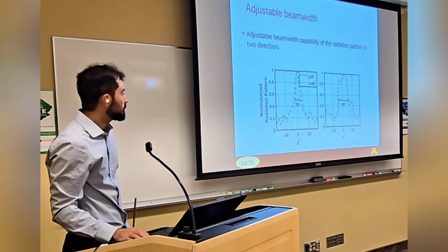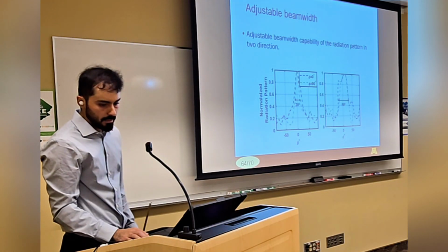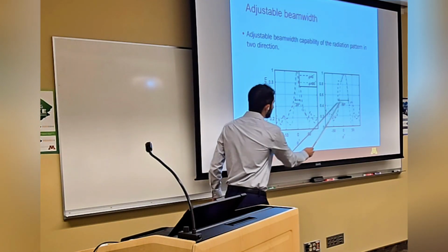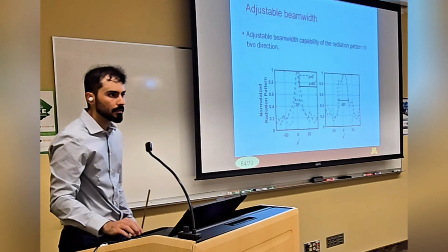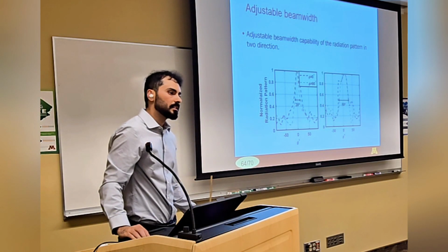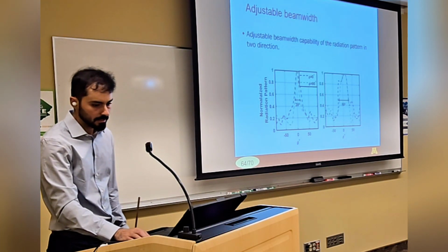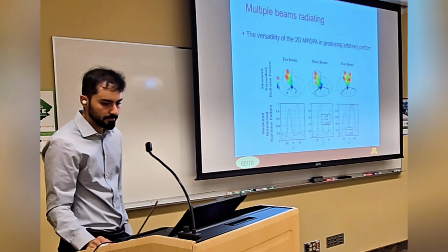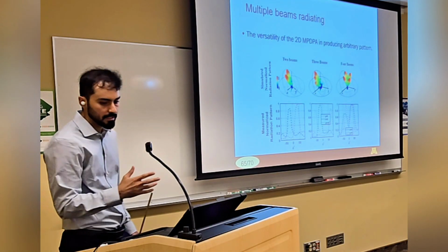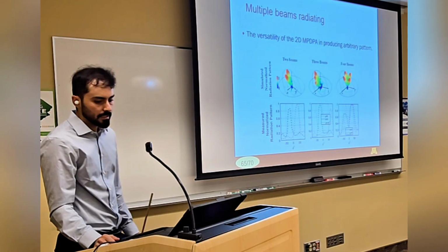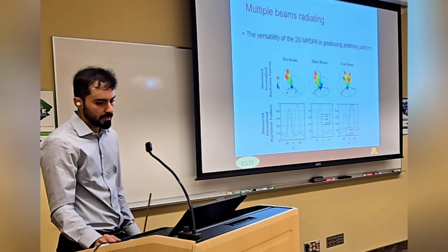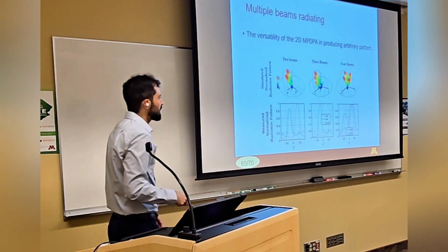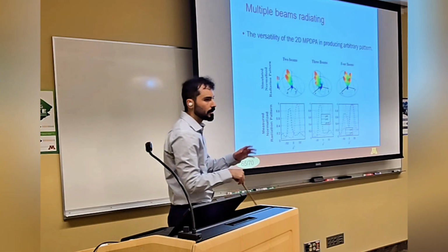And this figure shows the measured result for the radiation pattern at the center frequency, obtained with two different beam widths. And what is the center frequency? It's 7 gigahertz. And also this figure demonstrates the ability of the antenna to produce arbitrary patterns with multiple beams in different directions, where each beam in the multi-beam can be optimized with different beam widths and different directions independently.